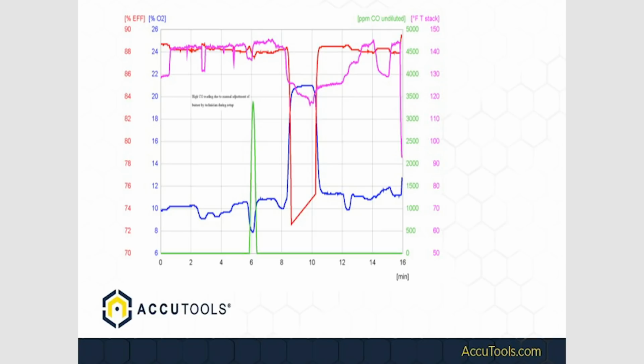Now here's what I want you to understand. This is a sealed combustion appliance. Sealed combustion. So it's exhausting outside, bringing air from outside. This pressure was overcoming the sealed combustion of that appliance. This is actually, when we tested it, because the other thing they did was they abandoned the chimney in the building, abandoned the chimney altogether. This is probably a 10-story building, huge chimney.